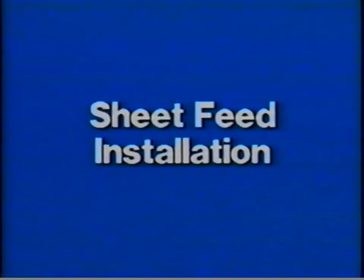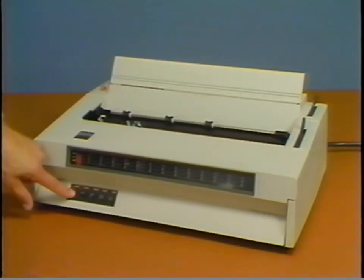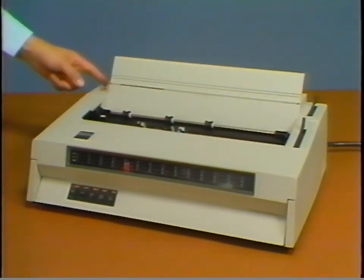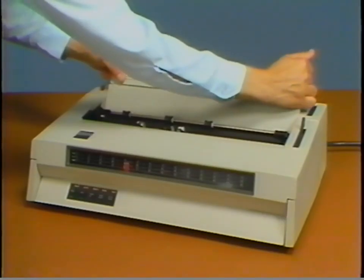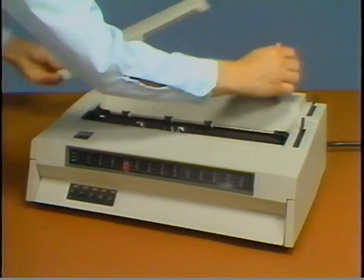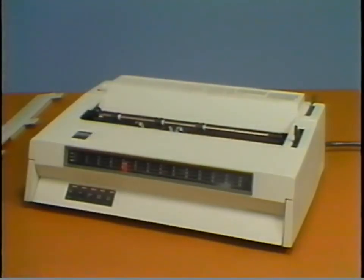The Wheelprinter E is also available with a sheet feed. To install the sheet feed, place the printer offline and turn the power off. Next, remove the paper table and move the paper bale to the front position.